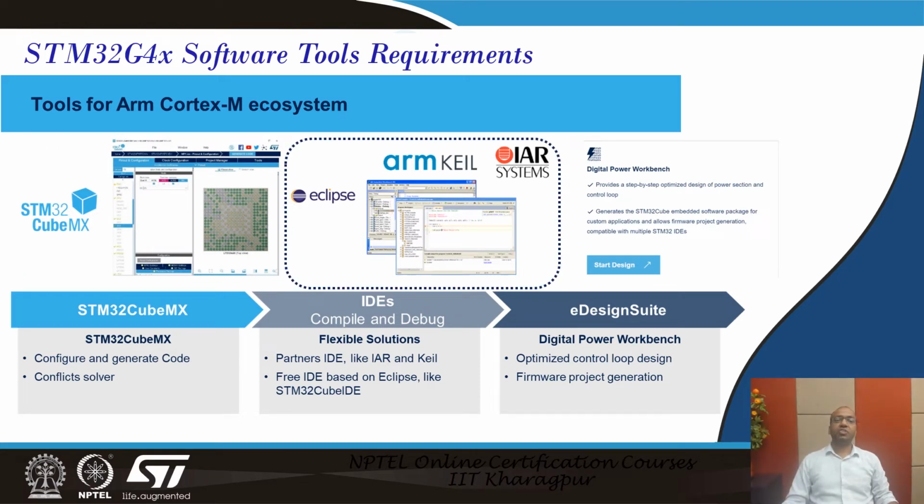The second software tool requirement is the IDE, where IDE stands for Integrated Development Environment. STM32CubeMX generates the initial workspace in three different IDEs: IAR Systems, Keil, and Eclipse. IAR Systems is a paid version, while Keil is free for evaluation purposes only, while Eclipse is a freeware available from ST. Now, the IDE is required for the application development. It's more of a customized thing that is required for the end applications and for the debugging purposes.